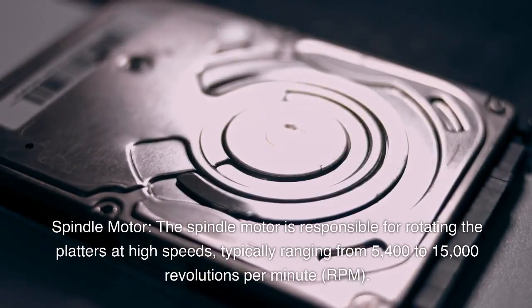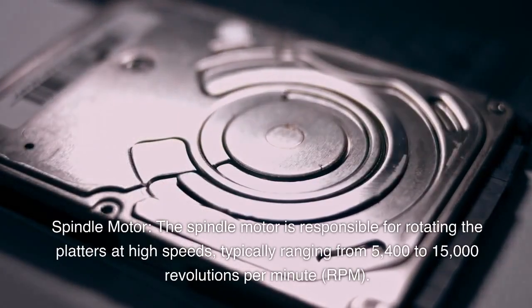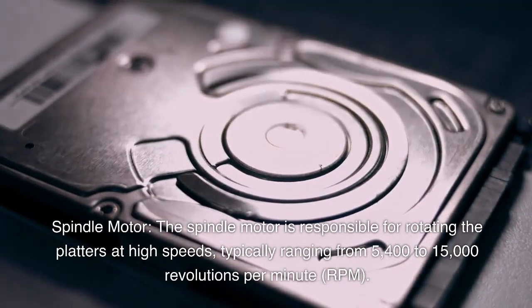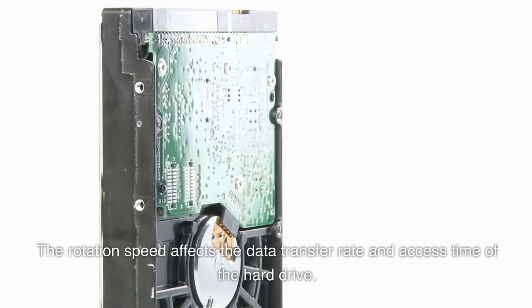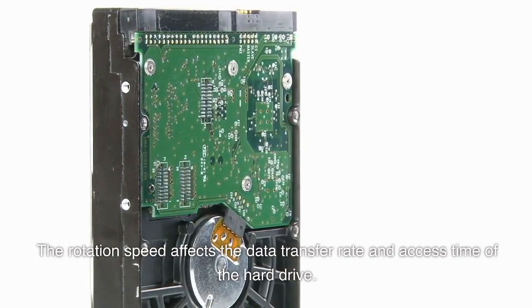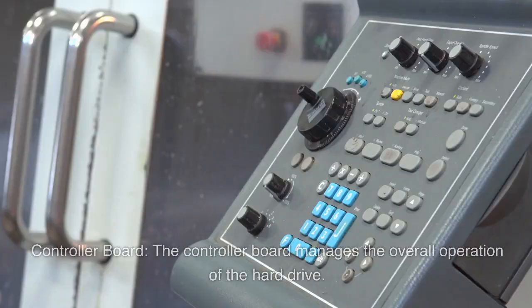Spindle motor. The spindle motor is responsible for rotating the platters at high speeds, typically ranging from 5,400 to 15,000 revolutions per minute, RPM. The rotation speed affects the data transfer rate and access time of the hard drive. Controller board. The controller board manages the overall operation of the hard drive.